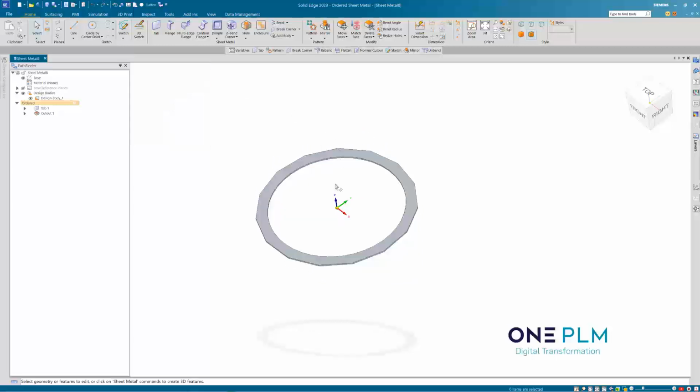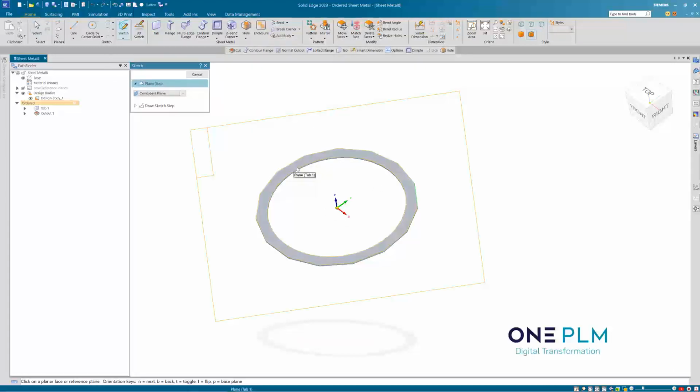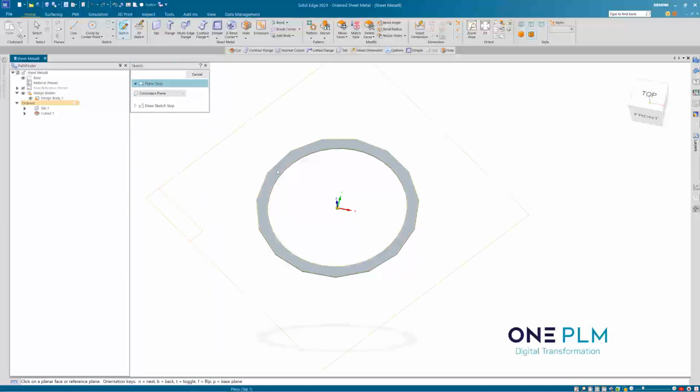Okay, sometimes if I know I'm going to be patterning 15 again and again, I will go and create a sketch, and I will create a sketch pattern for that item. So whenever we reference a pattern, we can easily do that. Notice my orientation is a little bit strange. So if we press the P key when we're hovering over it, we can match that to one of the base planes. So the P stands for the base plane on there.